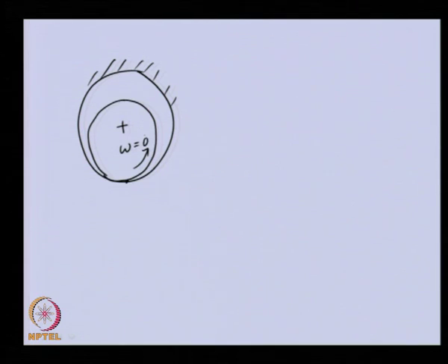But when the speed increases, the fluid in the clearance will try to go into this wedge, and because of this, pressure will be generated at the wedge, and the journal will lift inside the bearing.